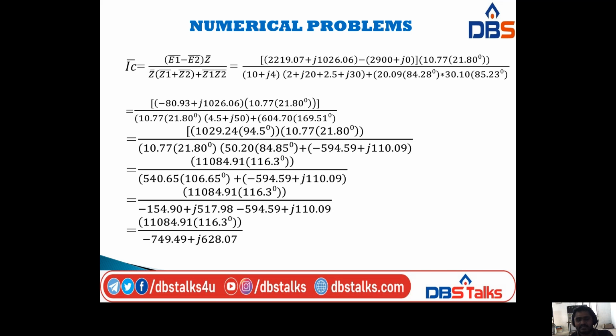Here E1 is 2219.07 plus J1026.06 minus E2 is 2900 plus J0, into Z bar, that is 10.77 at an angle of 21.80, divided by Z bar, that is 10 plus J4.